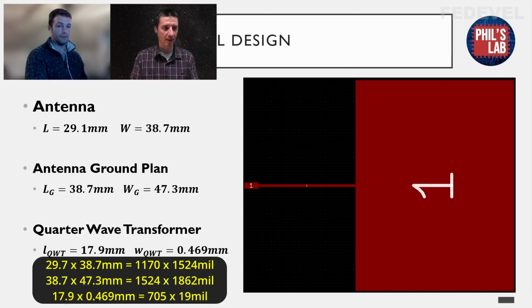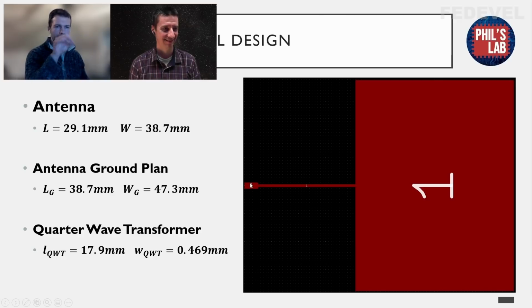The component is even bigger. Exactly, yes. And we'll see that in a second with the PCB, how far the ground plane needs to extend out. So plus 6H, essentially, all around. And then the quarter wave transformer is this rather thin trace in the middle, and that's at 18 millimeters with a certain width. And then I just added this tiny, it's 1.08, I believe, width trace. This is the 50 ohms that will then narrow down and feed into the QFN package.